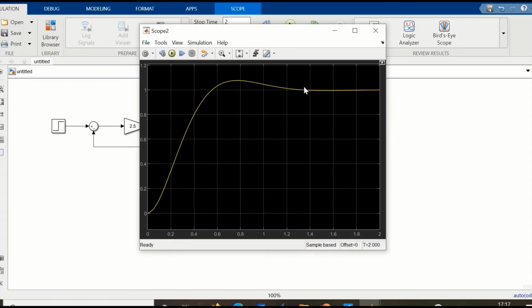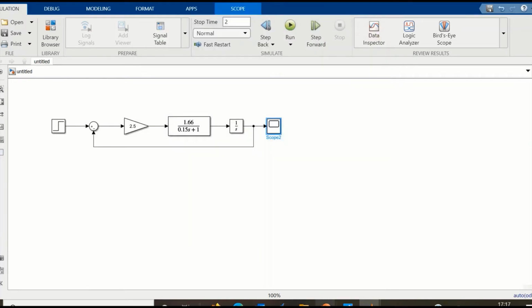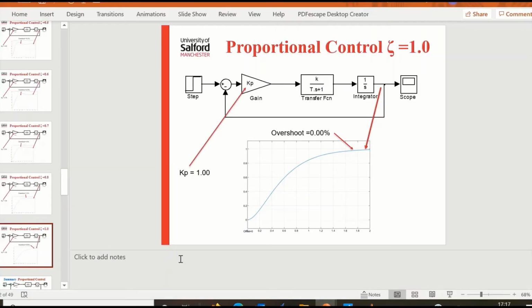It's going to give me that, so that's got about an 8% overshoot and the rise time of about 0.75 of a second. So that'd be my compromise, but everyone's got their own choice. But that'd be one of my better results. I was doing this, and that's with a gain of 2.5. So if we just go back to the